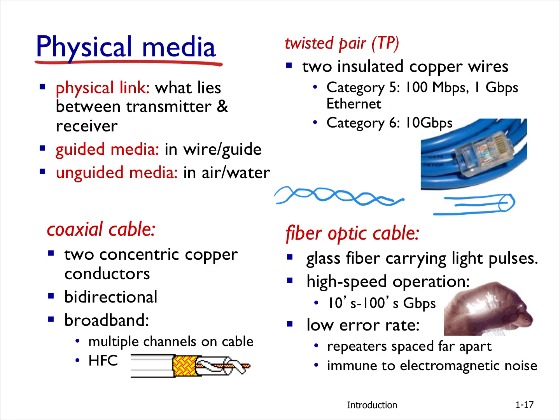So there's a core and there is a shield outside. The shield can be solid, but for flexibility and other reasons, if you look at the cable that comes from your dish to your satellite receiver, you will find that the cylinder is actually a mesh of very fine wires, causing it to look like a cylinder, but it's not a solid cylinder, okay? And then there is a core cable inside. Anyway, the concept is a shield and a core cable inside. That's called a coaxial cable.